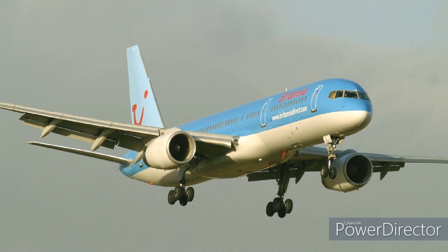The efficiency of all of these seals depends basically upon two factors. Firstly, the mechanical design of the seal, and secondly, the air pressure, which is essential if it's to work at all. Oil loss from a serviceable engine working at high power settings is almost negligible. It's during periods of low engine power, for instance, use of idle power during descent from high altitudes, that the greatest oil loss from a serviceable engine is suffered.